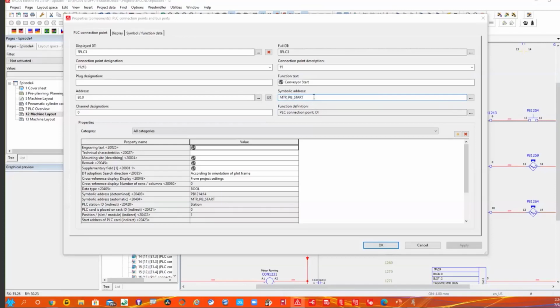Just an example of need-to-know information. One of these is one that I actually personally had to tackle myself. The symbolic address cannot take any spaces. So in the transfer of data from EPLAN, and apparently it's with other tools too that I found out, there are no spaces available. So when you use an underscore, it gives you that effect. So these are knowledge-based items that you can ask us about in support, and even with the coaching service, we can look at this more in depth.